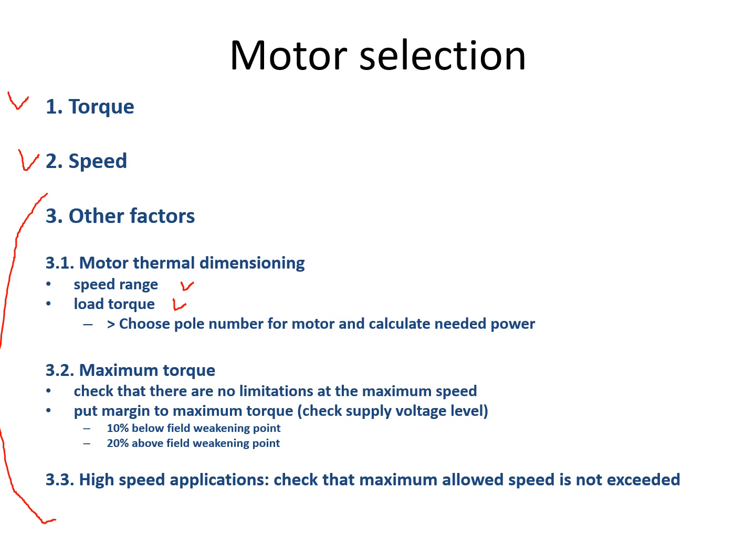A motor which can be quite suitable for running at the rated speed of 1500 RPM can be too small for running with the same torque at low RPM range due to, for example, cooling issues or some other issues. Some motors may have problems when run in overspeed, when we go beyond the rated speed and run at 10 or 20% higher speed than the rated. These things should be taken into account.